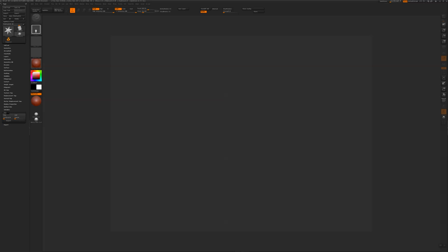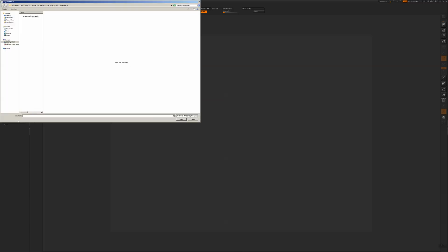Okay. The first thing we're going to click on is MRG. It's a button meaning merge points. So you're going to left click on that, and you know you've left clicked on it when it turns orange. Then there's two sliders. Try to quad. You're going to slide it all the way over to the max, 90, and weld. So you're welding the model all the way to the end, 0.01. You're going to hit import.